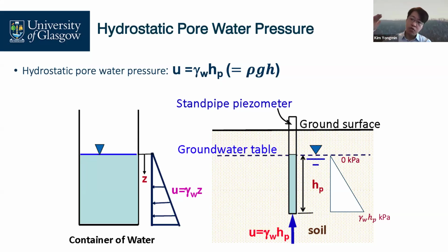You feel some pressure, which is the hydrostatic pressure. If you go to the bottom, for example 1 meter, with a water unit weight of 9.81, times 1 meter, the pressure would be 9.81 kilopascals, roughly 10 kilopascals at the bottom of the swimming pool from the water surface. This is the hydrostatic pressure.